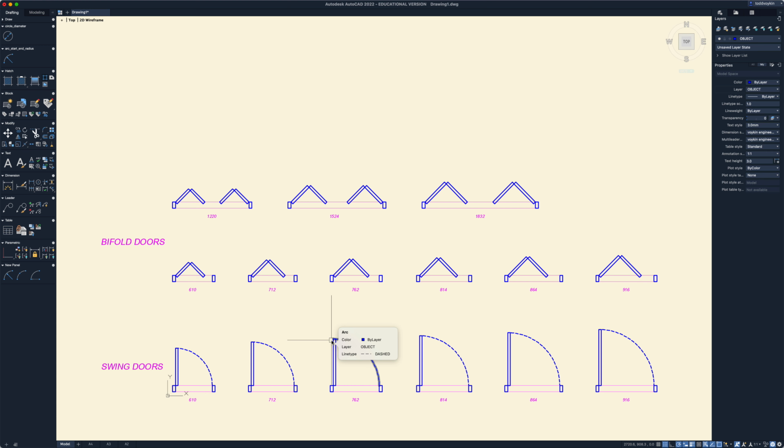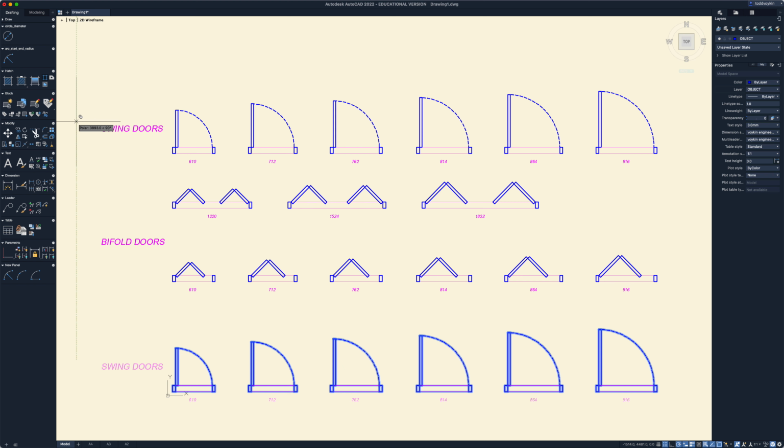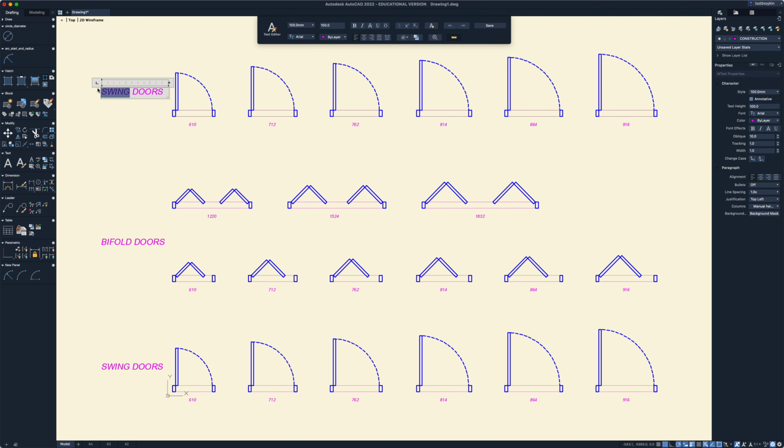So we need to draw that, and we're going to be using the same size doors as we did down here before in the swing doors. So we're going to do the same thing. We're going to copy all these doors right down here, and we're going to move that up to here, and we'll keep a consistent spacing. I think I was doing 1500 millimeters, so I might as well go 4500. Multiple of that looks good. This is going to be a pocket door.